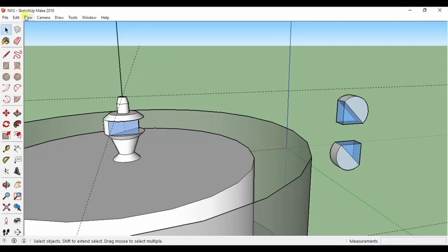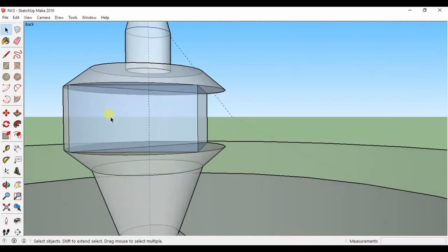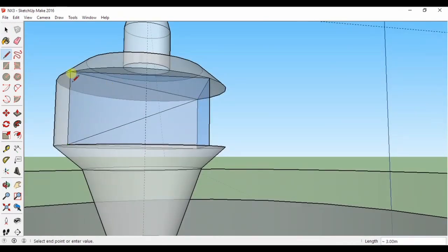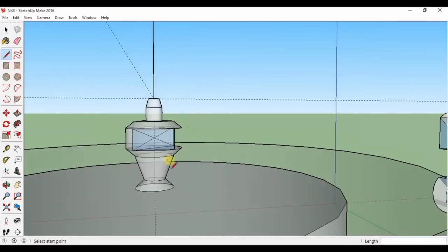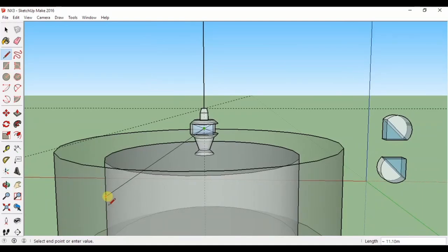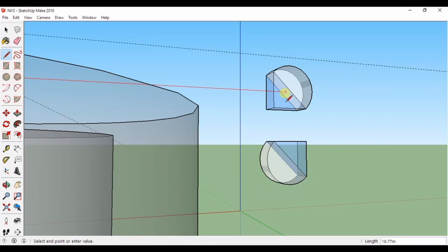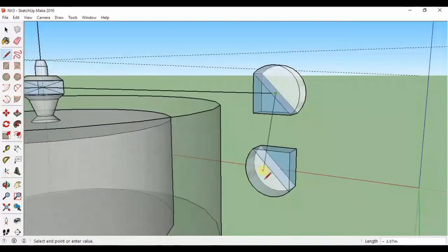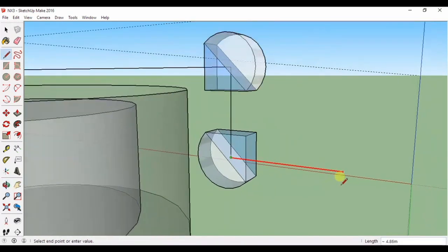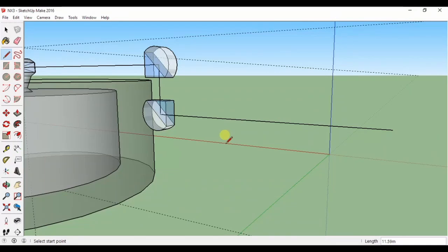Now, before I can align the mirrors properly, I can create the lines representing the laser beam. Firstly, I should find the midpoint of the mirror by turning on X-ray again. The red axis and green axis will be my guides. Now I can align the two mirrors, making sure to grab the mirror surface of the moving mirror at its center by drawing guidelines across the crystal surface with the Line tool. Once I've aligned the mirrors, I can delete the lines. It's a simple matter of continuing the laser beams using the inference directions now, and we're almost there.